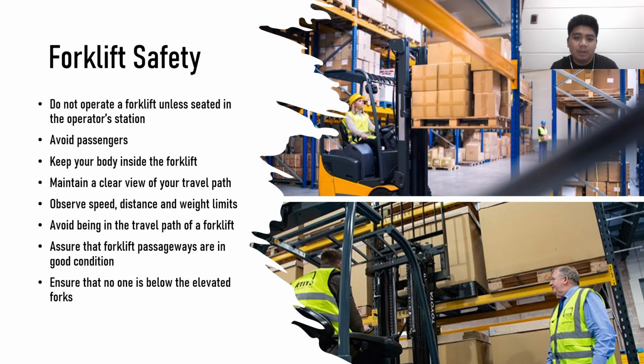Fourth, always look in the direction of travel and keep a clear view of the travel path. If the load is blocking your view, travel in reverse if it is safe to do so. Fifth, always observe posted speed limits at your workplace. A forklift should not be driven faster than a quick walking pace.